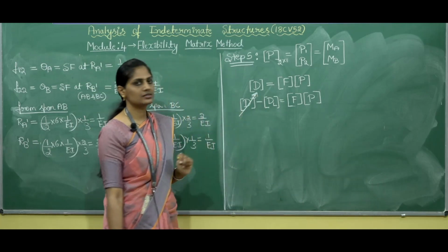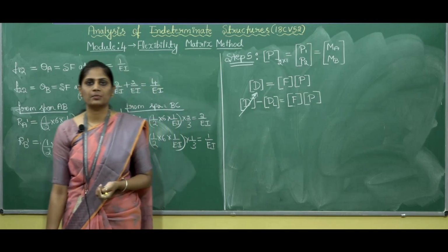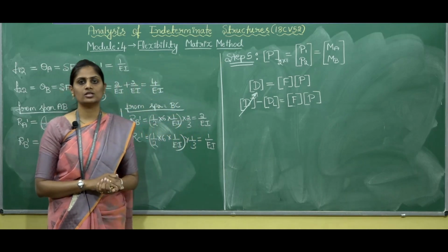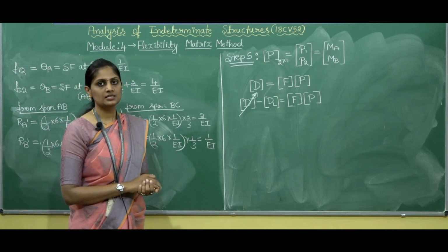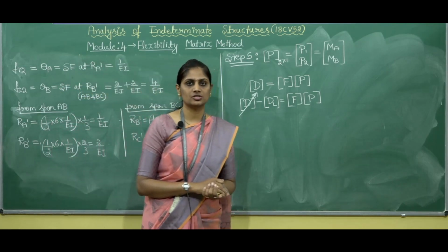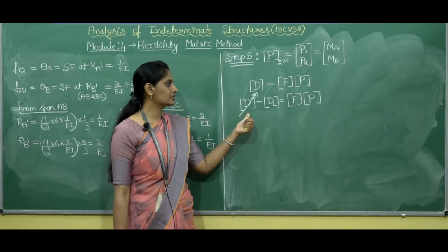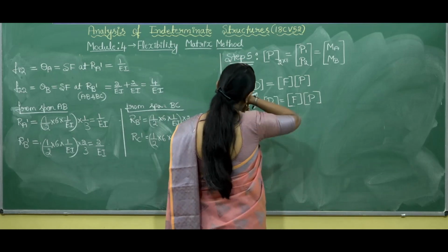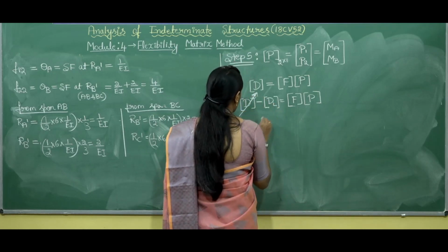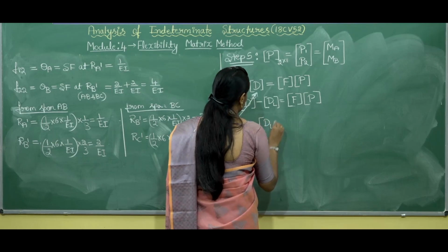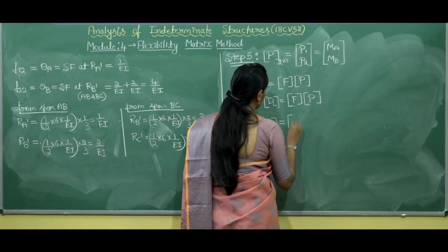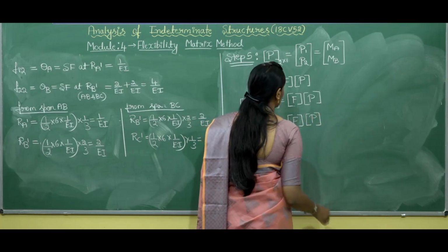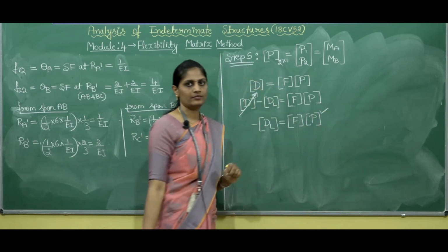That means the D matrix represents the final displacement due to reasons like sinking or rotation at the supports. Since the given problem has no such conditions, D equals 0. So solving this, we get minus DL equals F into P. I need to find this P.